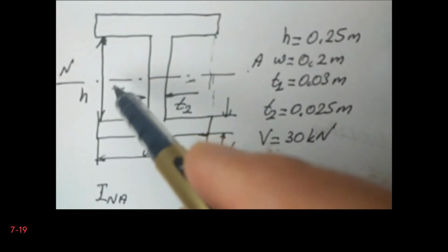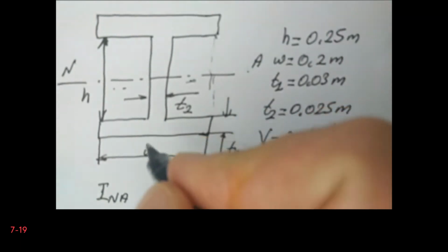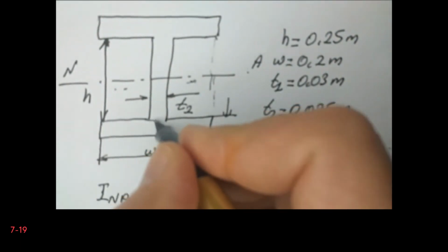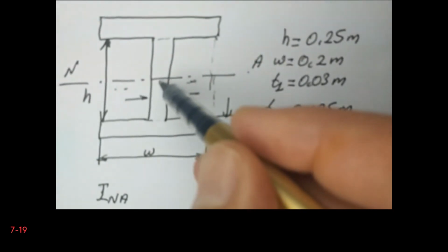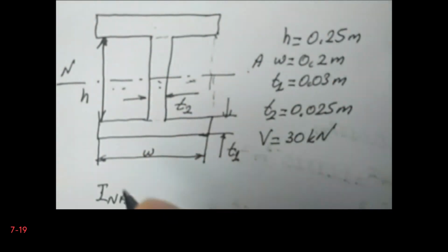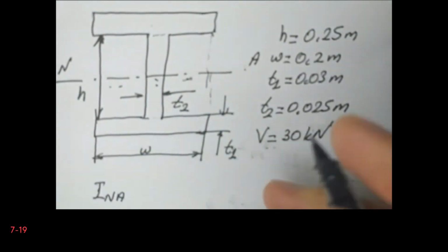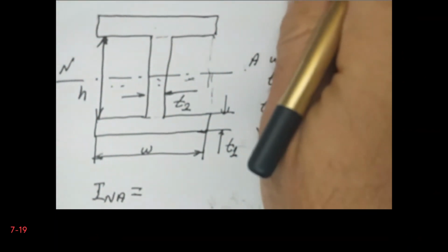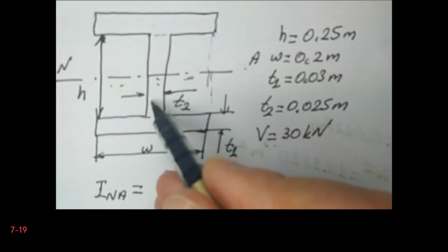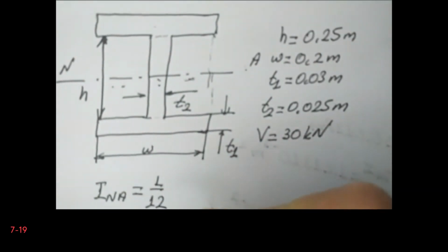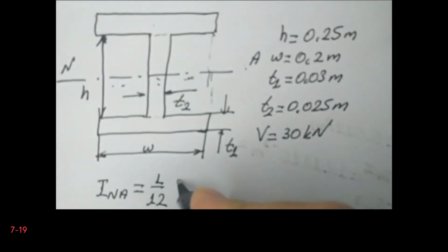This is one way of calculating the bending moment of inertia. And the second approach is dividing this cross section into subsections and calculating the bending moment of inertia. In fact, one choice is one web and two flanges independently. This is what I'm going to do, but I will write both equations for you. They are both identical, in fact. First, I will calculate the moment of inertia of the web. So it is 1 over 12, the width is T2 multiplied by h cube. This is h.